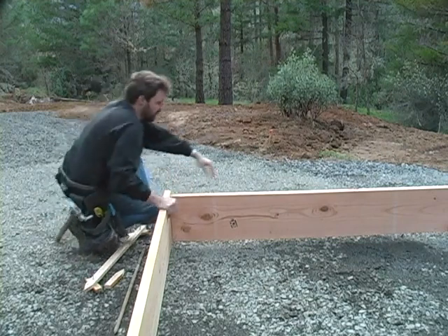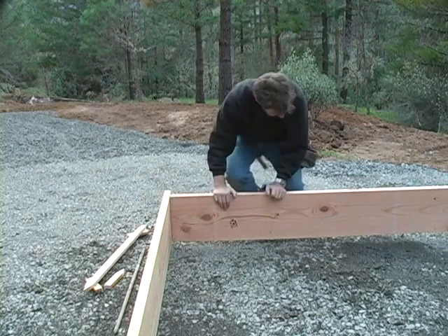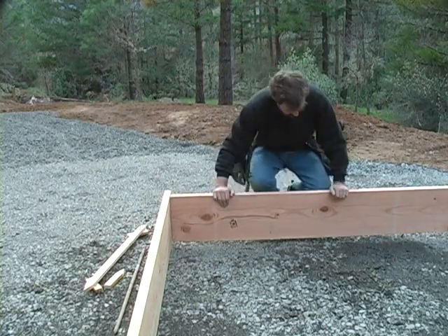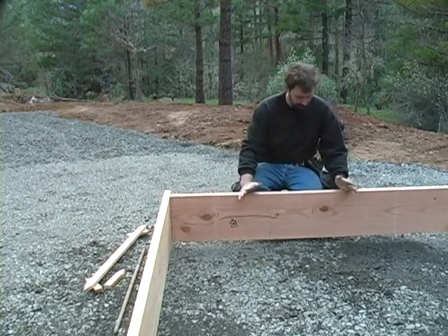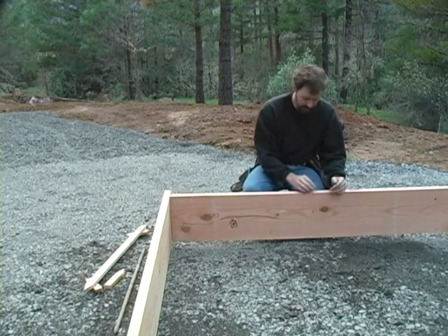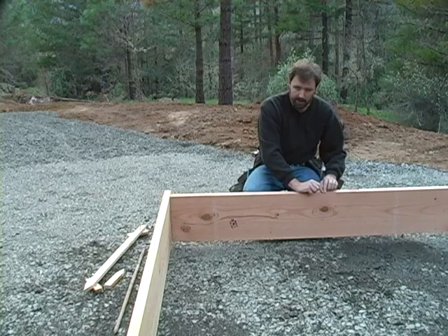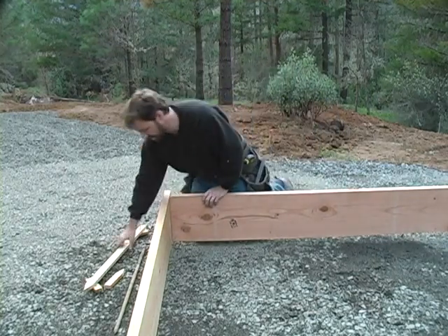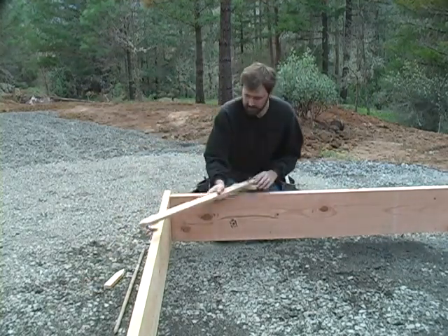We know that the bow is going to the outside, and both of these boards are bowing pretty significantly to the outside. So what I can do is actually come in here right at my 3-foot mark, have a helper at the 4-foot mark, and just put a little bit of pressure to knee that board back in. And as we measure that, it comes out okay. So then what we want to do is brace it off in position.